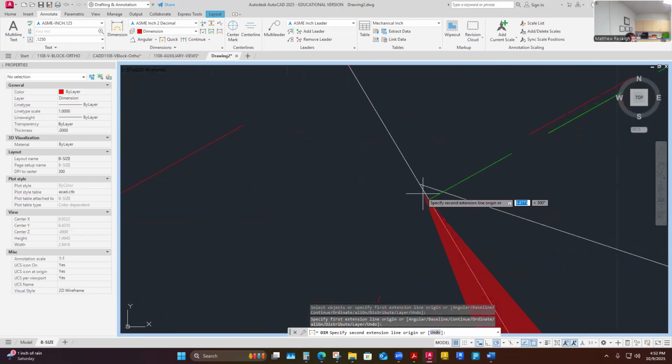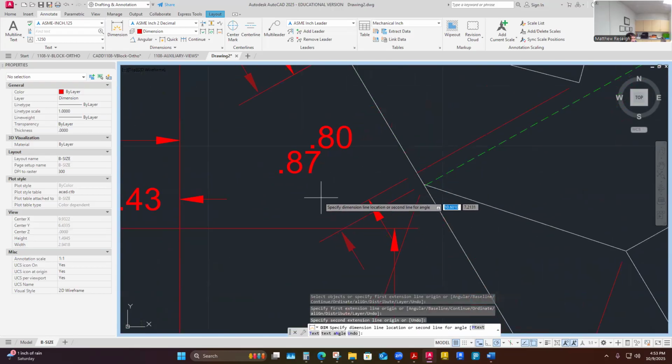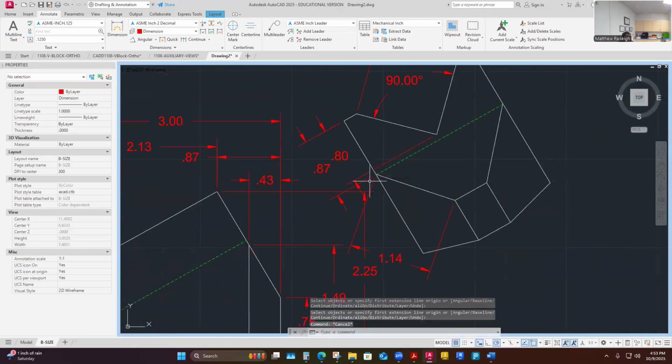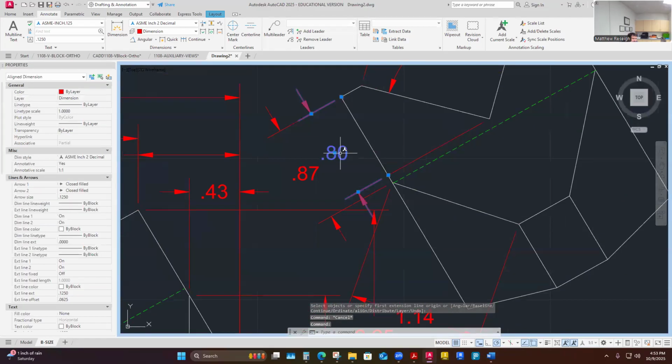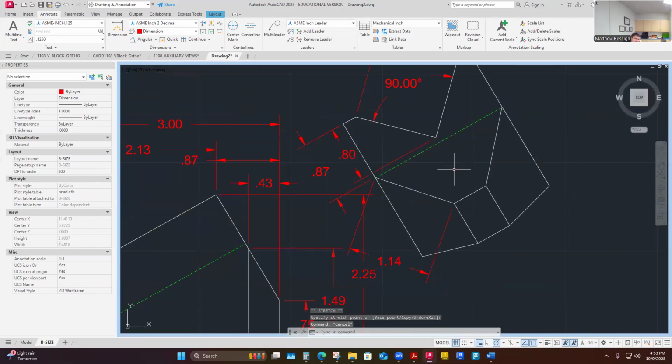And it's where these true lengths really came to show themselves, right? Like right here is where that is, and it's 0.87. It's a little bit further out than that one. So it's just slightly bigger than 0.8. 0.8 is really the depth of the V in this orientation, and then 0.7 goes down to that side, which we have in either view to pull up, but I kept my aligned dimensions on my auxiliary view. I'll keep my mess over here. And then I've got a big mess going on here that I'm going to have to decide if it's going to push over to the other side of the auxiliary view, or something might have to happen to clean this up.